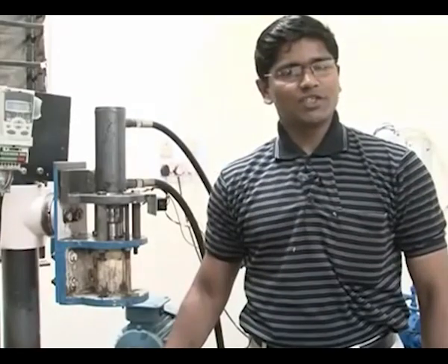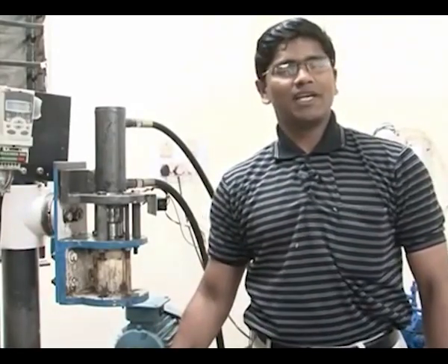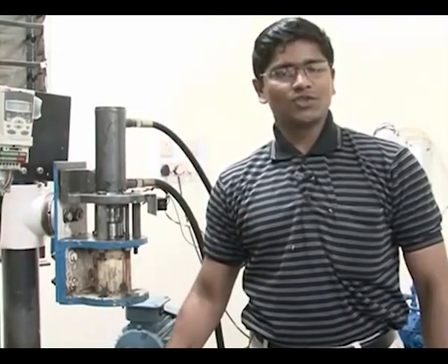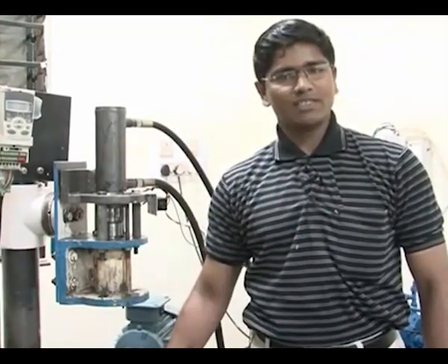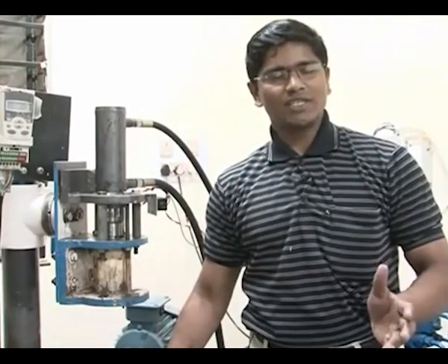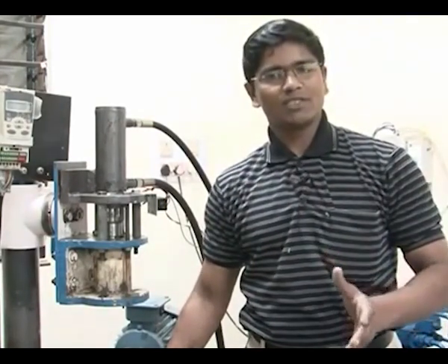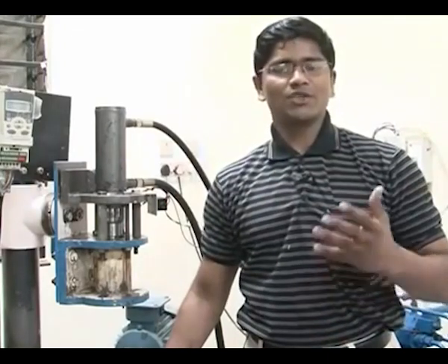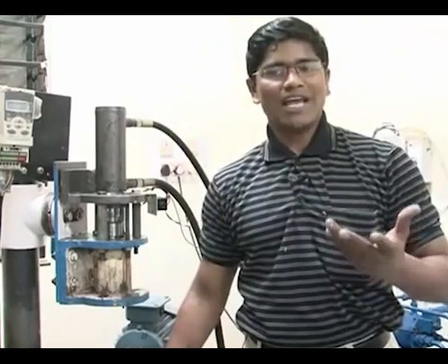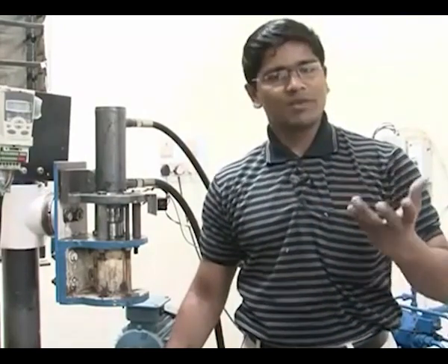This abrasive flow finishing was invented in 1950s by Extrude Hone company in US. At the time, this process was used majorly for the deburring process. Because it was a machining process, it was called the abrasive flow machining process. Nowadays, the same machine we are using for the finishing process, even for nano finishing process. Thus, this process is renamed as abrasive flow finishing process.